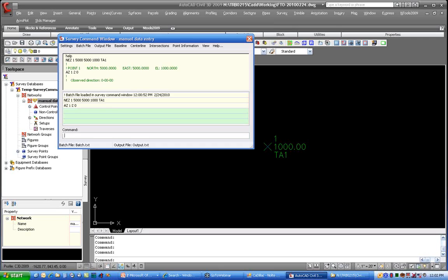Then let's set our station up now on point number 1 with an equipment height of 5.22 feet, and use the same name again. And then we'll backsight point 2. Now you'll see on my screen I'm getting those interactive graphics. There's my station, I've got my angle set, I've got my backsight set, and I'll throw in a point here. I'll do an ADVA, which is an angle distance with a vertical angle, and go to point number 3.